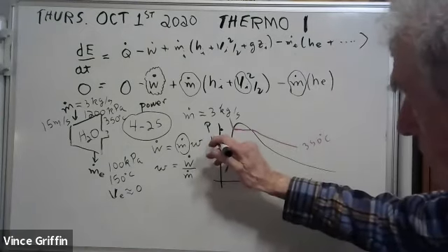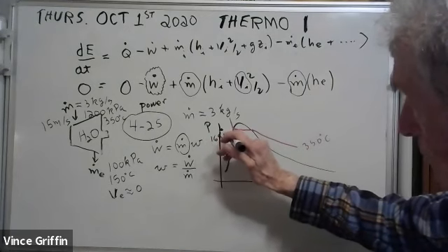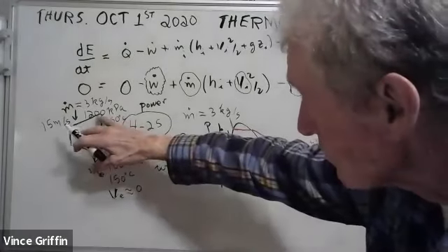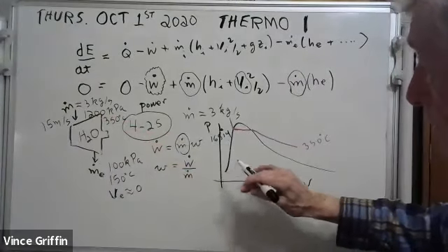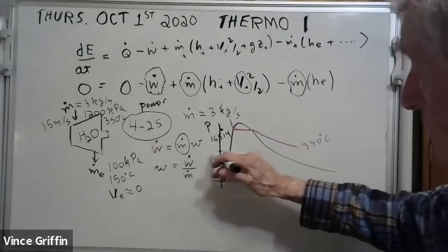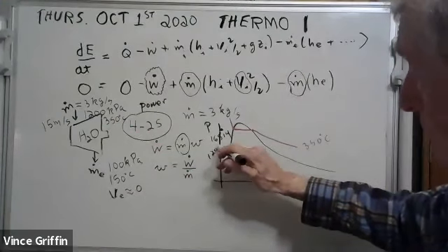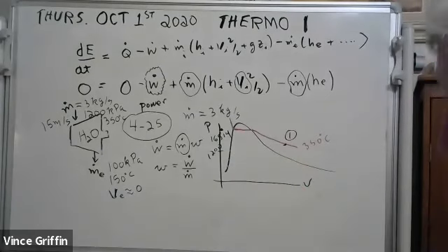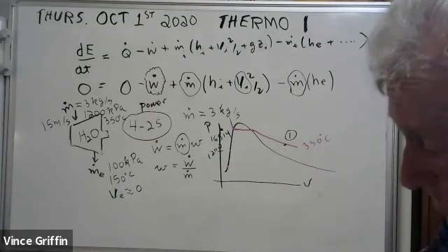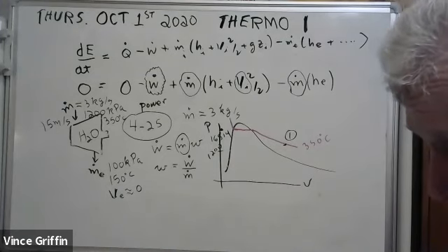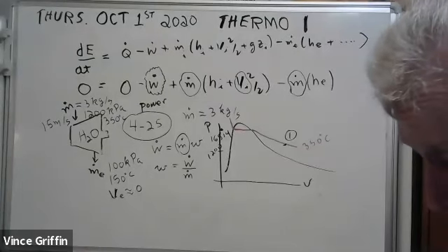This pressure here is 16,514 kilopascals. We just have 1,200. You know what? 1,200 is smaller than 16,000. It's down here someplace. So that means we're out here. Superheated vapor. Go to the superheated vapor chart and look up 1,200 kilopascals.